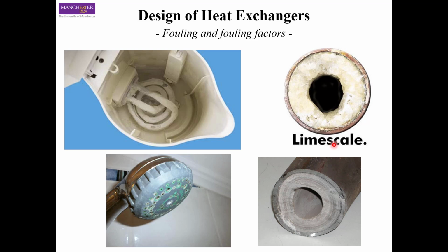Okay, so if you look at this situation here, for example, you have the convective resistance of the fluid that is inside the tube, and then this fouling layer adds an extra resistance that is due to the fouling layer, and then we have again the tube resistance and then the conductive resistance. So this fouling layer imparts new resistance to the heat transfer.